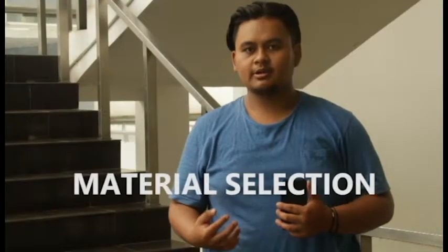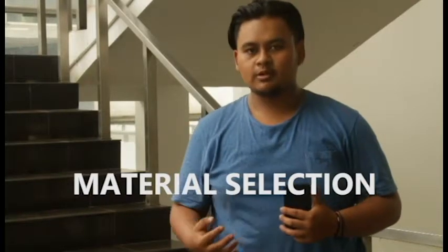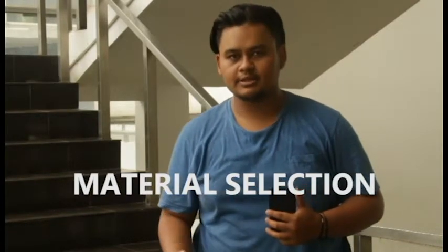Material selection. Why is material selection important? Material selection is important to fulfill a design requirement for a certain application. The application for this case is the Pelton wheel. The Pelton wheel requires the material to be waterproof. Materials for this case also have to be cost efficient. For a material to be cost efficient for a particular application, it needs to be cheap and also easily formed into a shape of our wanting. Why is this important? Why will this lower the cost of production? Because if the material requires processes that involve power machinery, that will also increase the price.